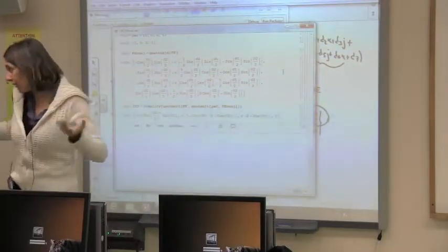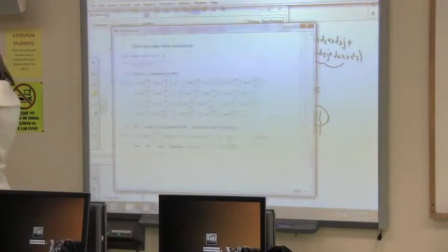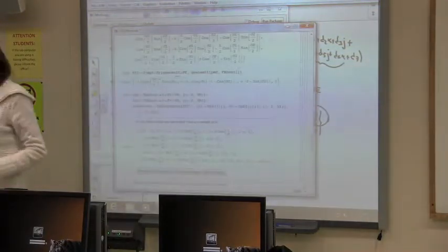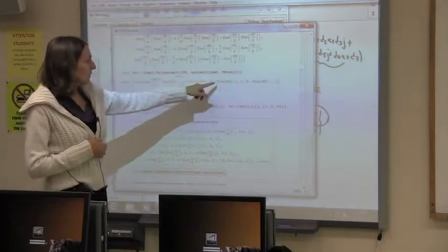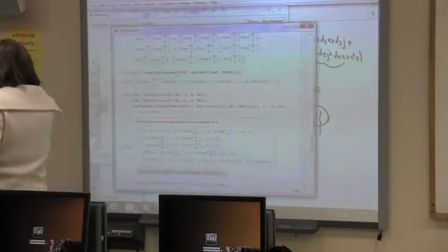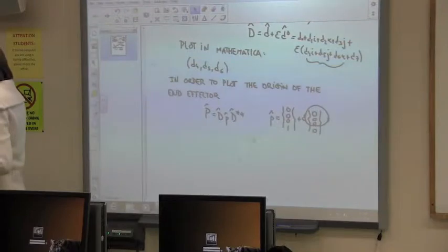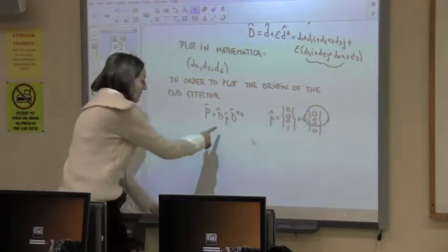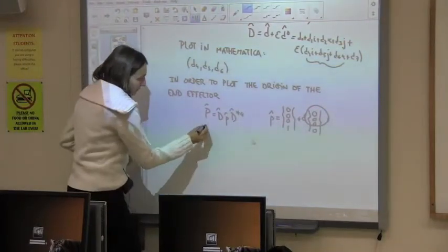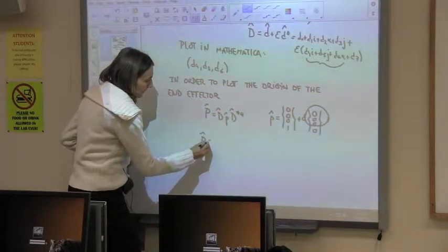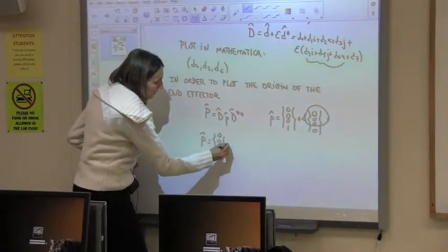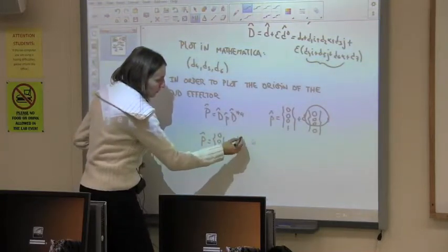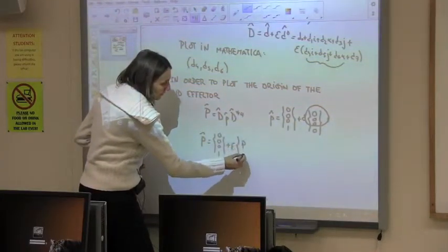So now we are going to give values to theta 1 and theta 2, which we already have up here. You can reuse the epsilons. Okay, let me show you what we are getting. We are getting something with epsilons. If we write it in here, what you get as a result is a dual quaternion that will look like 0, 0, 0, 1 plus epsilon, and then the location of the point should be here, P0.